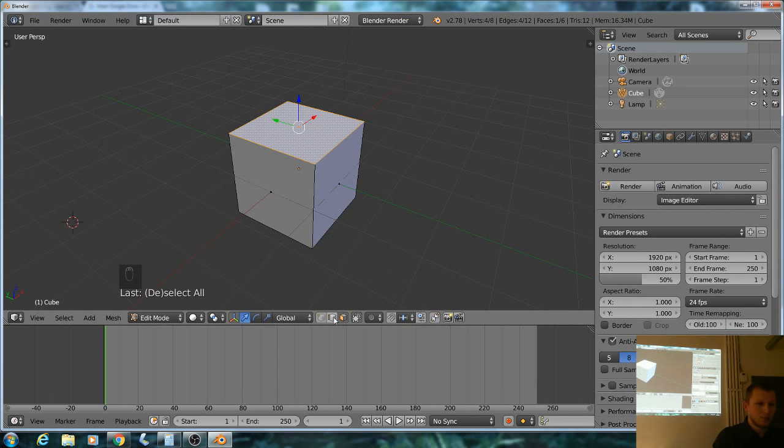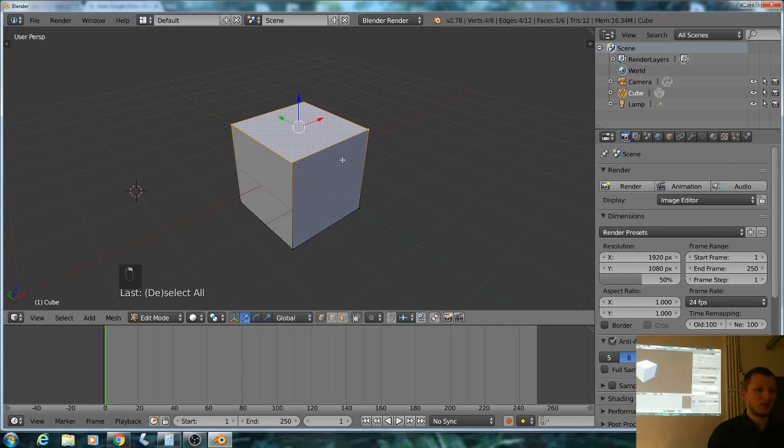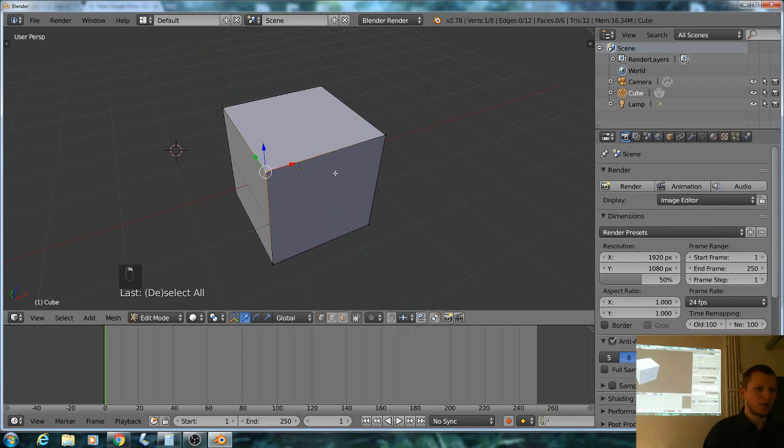Basically you can also choose edges and faces by selecting many vertices by holding down shift. Then you can keep the previous selection, I guess, would be most accurate. So for example, if I select two vertices, it's basically the same as doing one click in the edge selection mode.